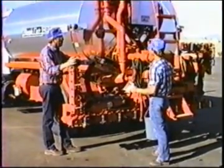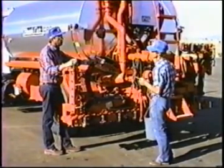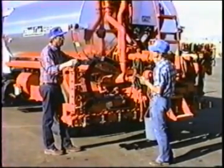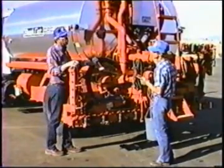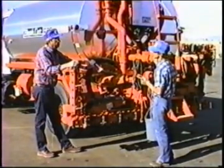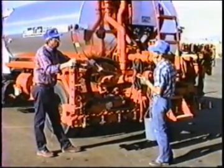If we're going to lengthen the bar, we were only pumping 135 gallons a minute, which is enough for 12 feet. If we lengthen the bar, now our pump's not turning fast enough. So as we lengthen out, we also have to speed up the pump. So in the manual situation, if you're going to be changing widths, then set the pump up for the maximum width that you will be spreading. That is, set your pump speed.